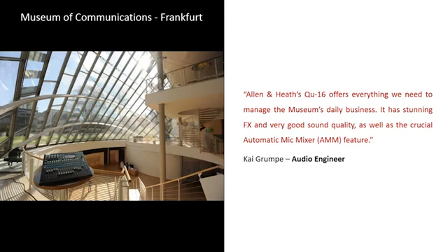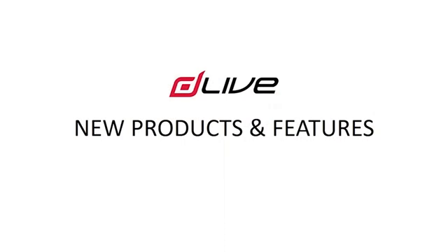So now DLive. David has touched briefly on the flexibility of the system for permanent installation, and we are seeing a lot of customers deploying DLive in fixed install, where they need not only a mixing system but also a distribution system where they can take something like up to 800 system inputs, be it digital or analog or Dante, MADI, Ethersound, any protocol you like, and route them to about the same number of system outputs in a big installation or matrix system.